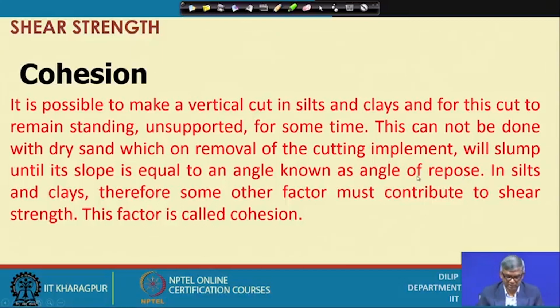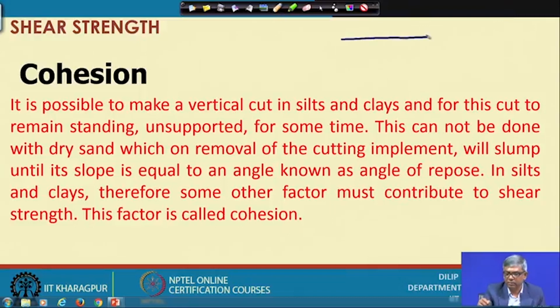So, that means in a silt and clay you can make some cut. Suppose you make an excavation here, up to some depth it will stand without any support. But if it is a sandy soil, and you try to excavate, then the slope will fail and it will have some final inclination.